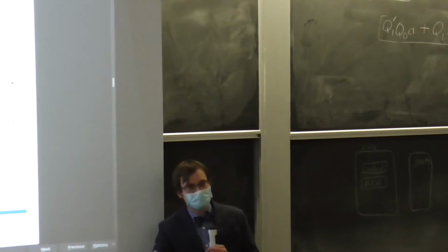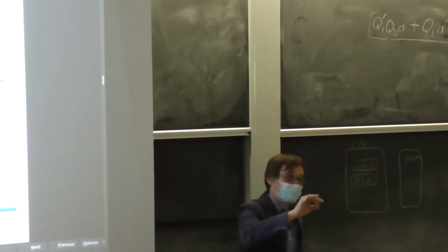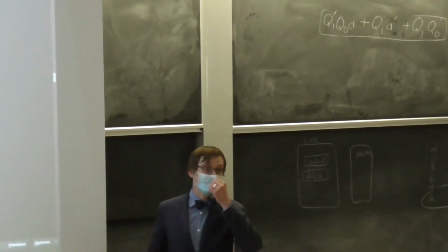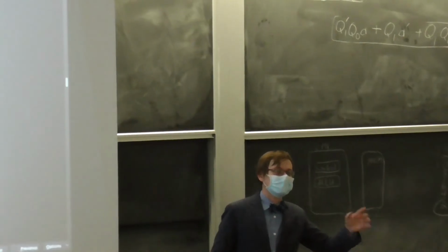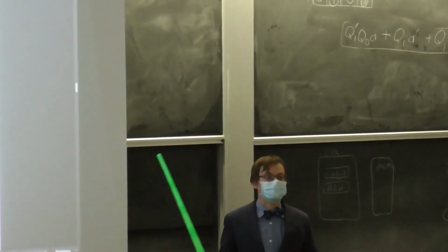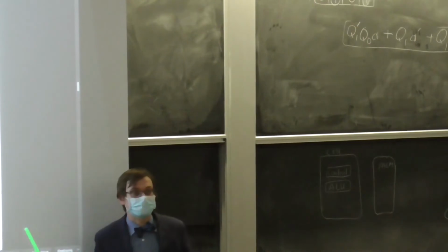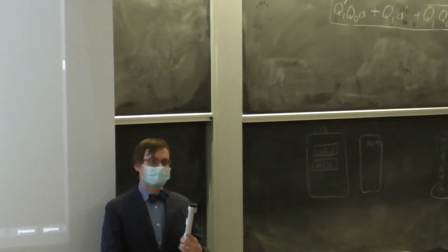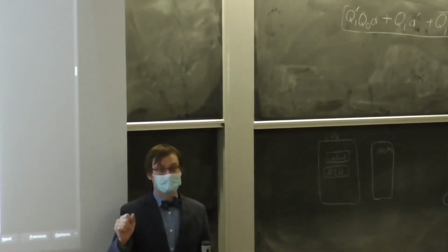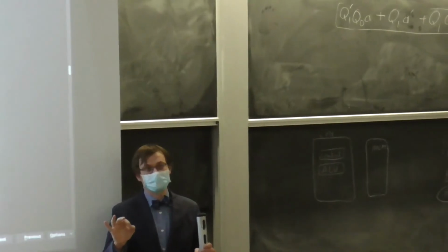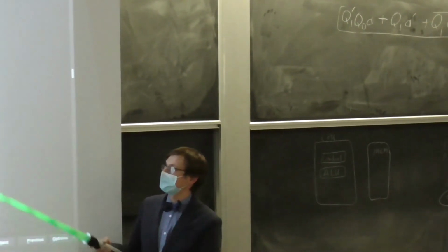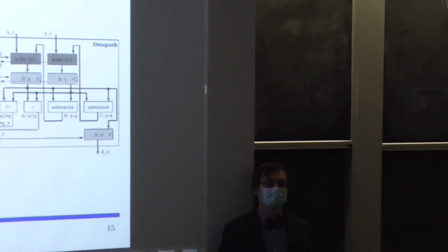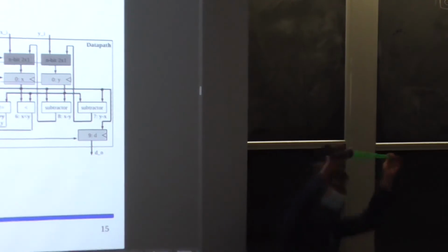It's not quite a one-to-one because there are some memory operations like load and store which would not need the ALU, right? Like if you're loading from external memory into one of the registers, that doesn't require an ALU operation. But add, sub, all of these operations, anything that's not just moving memory around, will be a specific module inside the ALU. So that's kind of where the instruction set comes from then? That is precisely the case, yes.